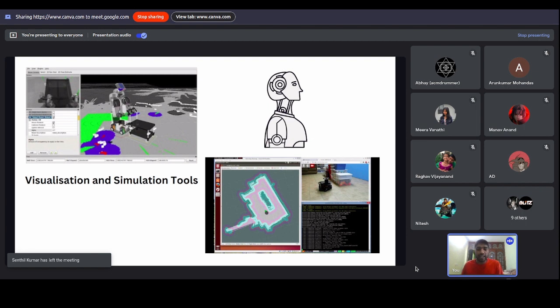For that, you want to know how exactly and how accurate your robot is in mapping the room. RViz is very useful to see what sensor readings your robot is getting, and whether it is actually getting the desired output for the code and the nodes that you've written.